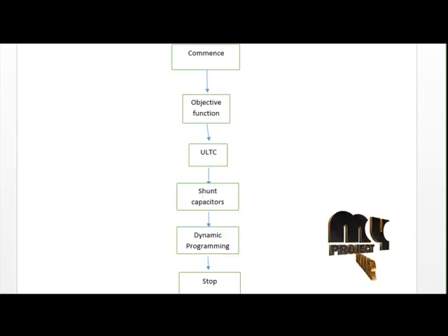A switchable shunt may be disconnected from the circuit when conditions warrant, while a fixed shunt is permanently connected to the power line. Shunt capacitor banks are mainly installed to provide capacitive reactive compensation or power factor correction. They are installed near the load terminals, in factory substations and in receiving stations, to provide leading volt ampere reactive.